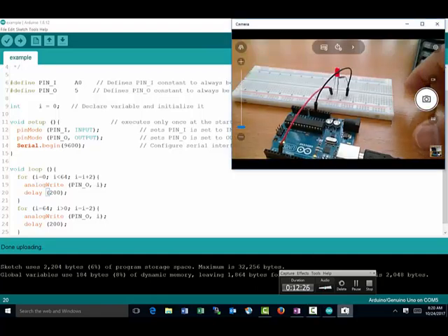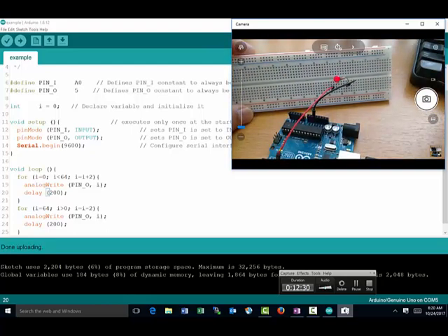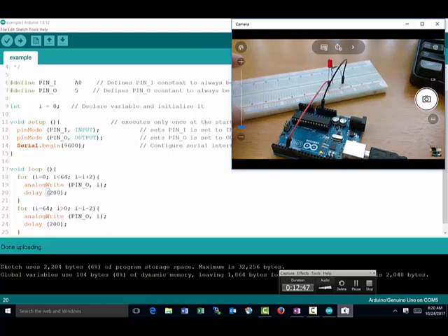You've got to be patient, but hopefully you can see how it's dimming down and back up to full power, and then dims back down and back again. So what we are doing with this code is stepping up first to 64, and then slowly stepping down until we get to 0, and then this repeats itself. That's what that LED is doing.